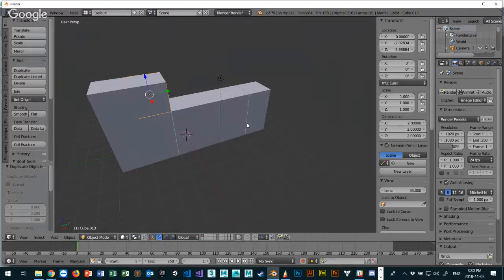Blender units. Hey, I'm just putting it out to you because Blender units have nothing to do with meters, right? Which means your scale, when you bring this into Unity, is going to be completely off. To work with Unity, we have to modify our scale so that the scale we're using here is exactly the scale we're going to use in Unity.